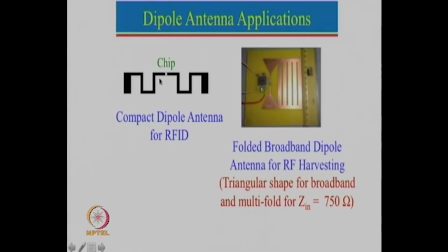So what is actually done, you can bend them around. So this length here on one side will be roughly lambda by 4, and this length is also roughly lambda by 4. So one can actually twist and turn them around. The total length should be roughly equal to lambda by 4, but it is actually my experience that this length should be slightly more than lambda by 4 because of all these bends, and the bends can be used in whatever fashion you need to do it.